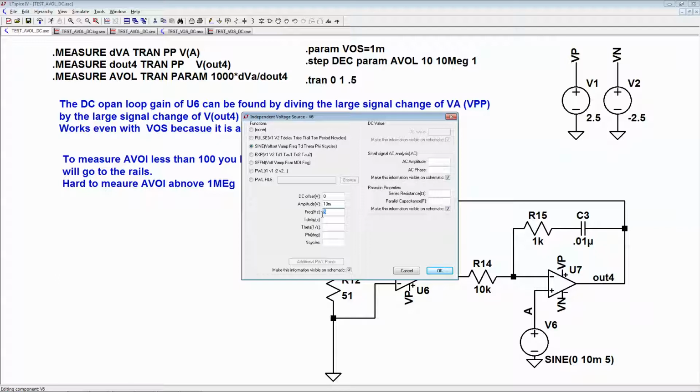But with the parasitics, or something going on here, as we increase the frequency of this, we're actually getting that gain bandwidth slope. So 5 was about as fast as I could go before it started affecting the measurement. Now, 1 is better, but if you've ever tested a 1 hertz signal, it is a pain. So 5 is pretty good.